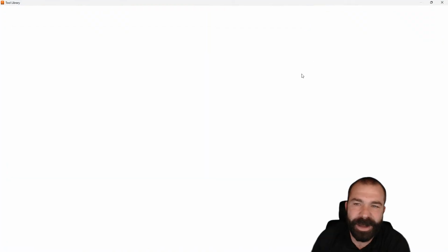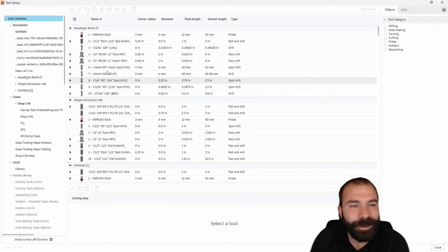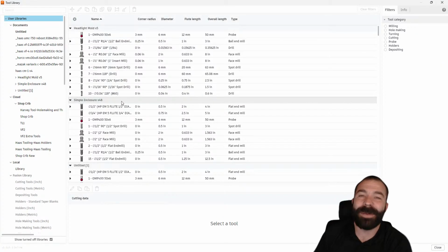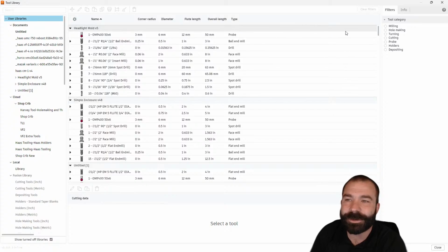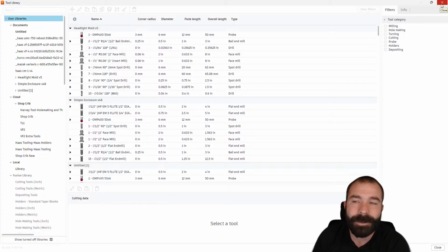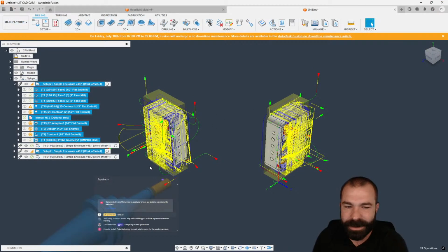So again, I verified here, we didn't get that lucky, where this problem has been fixed since. But it was very interesting to see when they were trying to reorder their tool changes, and it was just jumping all over the place. It wasn't staying on one part. It would do one tool here, and then it was wanting to do a tool change and then go over here, even though it was the same tool in the spindle. And that was causing a lot of problems in that reorder situation.